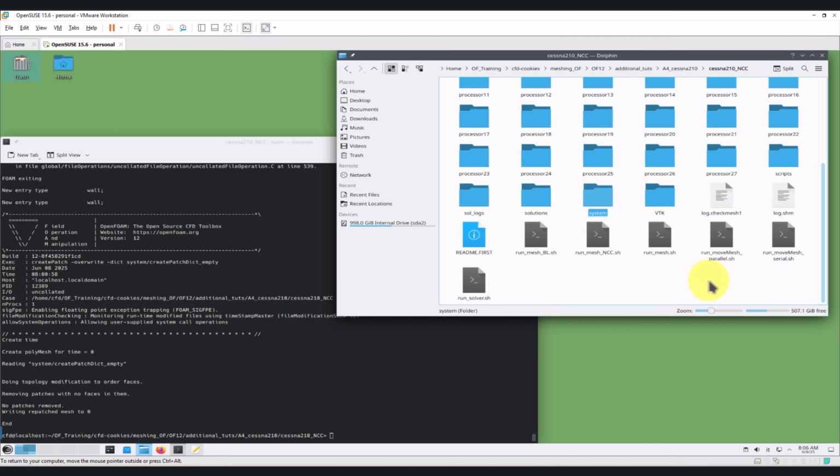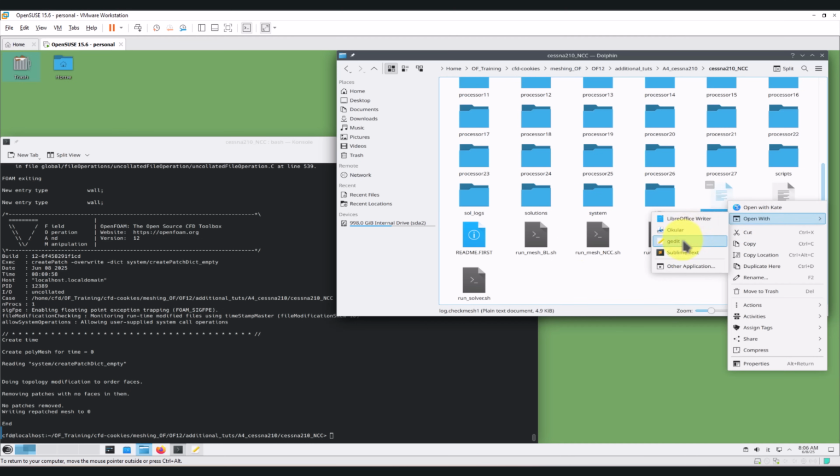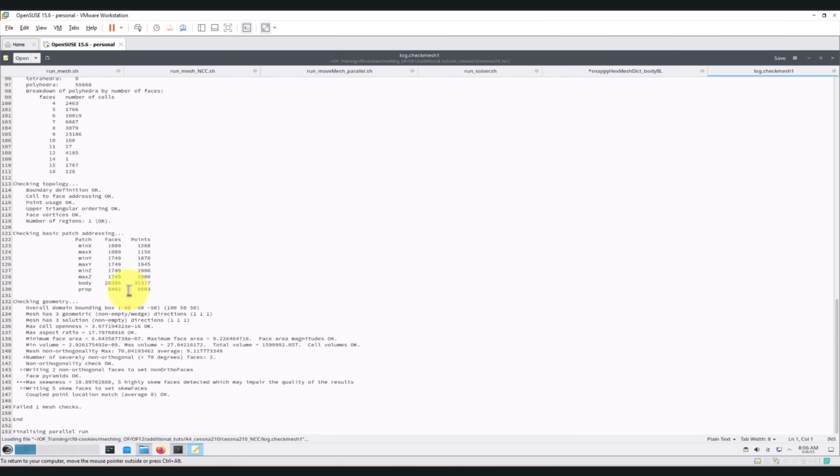Then let me go here. I have to check the mesh as always. Check the mesh quality and see that there is nothing to complain about. So probably skewness 10, that is not an issue. And orthogonality also will tell you, but 70 is very good. And the other one is probably a little bit higher, but something that I'm not worried about. And a few cells, I know that if I make it finer, it likely would be much better.